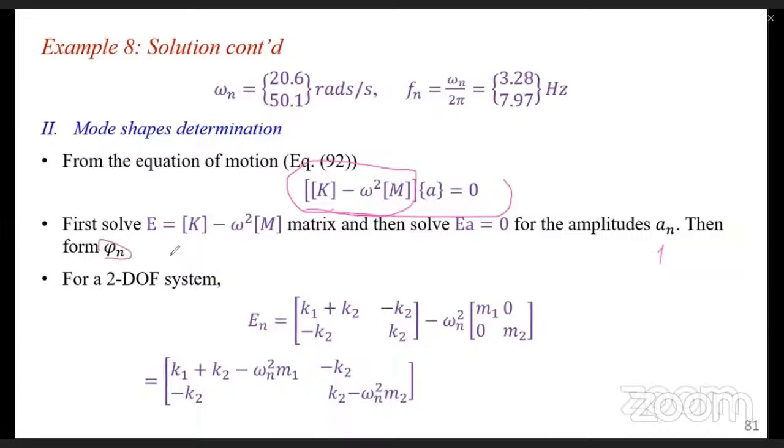For the free vibration, we express the displacement or the amplitude as a ratio of 1 and 2, or 1, 2, and 3. We can't get them in absolute terms. So for the 2 degrees of freedom case, we just need to see En, or E1. So for K, you substitute the value. Remember the matrix K is here. Then omega squared M, of course you have M1, M2 like that. Or you simplify that, it works out like this. So En is like that. Remember, E is just a representation of this part. I hope you are following also using your note. That's why I'm moving slightly faster.